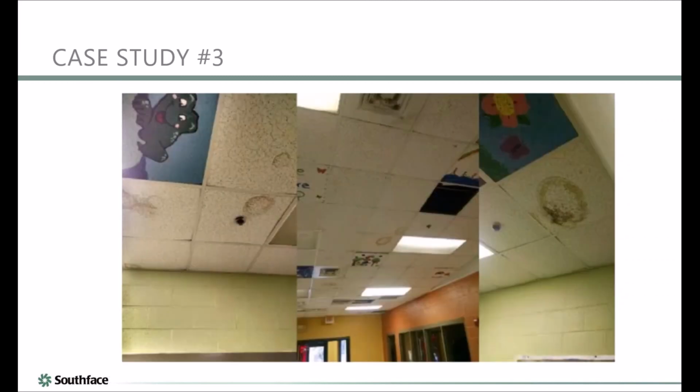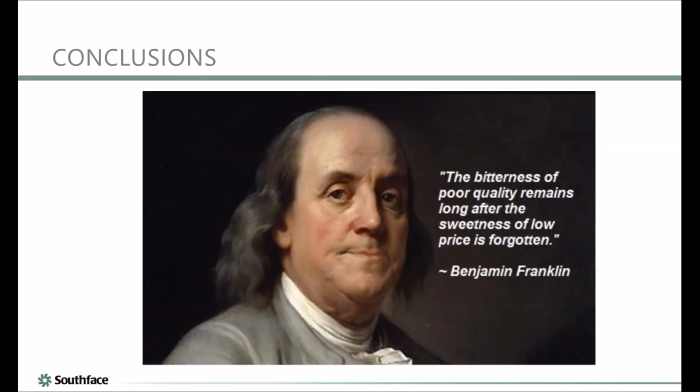And here's what it looked like from the inside. And I think they had a contest to try to paint over the water stains, it seems like. But again, that was the saggy tiles with the drops on them. That's all evidence of a return pathway that's not been defined, and a poor air barrier too. So Laura, hopefully we've made a case for our opinion on this, which I feel is pretty clear.